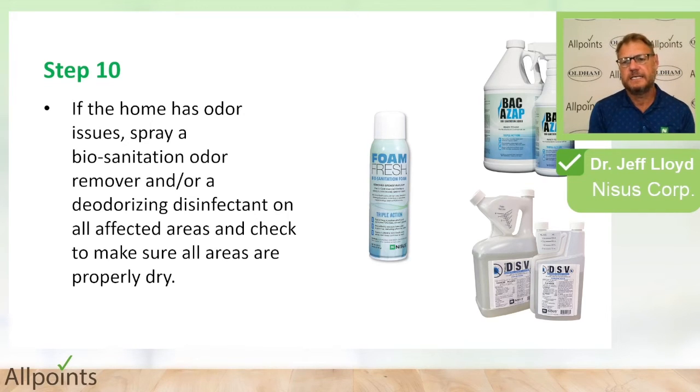Step 10, you can consider odor issues. Oftentimes you've got organic debris that's been deposited in the home, it's been damp, etc. So DSV, we talked about that earlier. Hopefully you've done a disinfectant type treatment in the structure already. That will kill the bacteria that often cause odors. Okay, so that's typically a good thing to do, and some of those bacteria can be pathogenic, so we want to kill those so we don't harm people. There's no residual protection from that. So once you've done the disinfection, you've killed the bacteria. If you've still got a damp situation, you've still got organic debris there, you could still have some ongoing odors. And so other odor eliminating products, or organic digesting products like Bacazap or Foam Fresh can also be helpful to you.